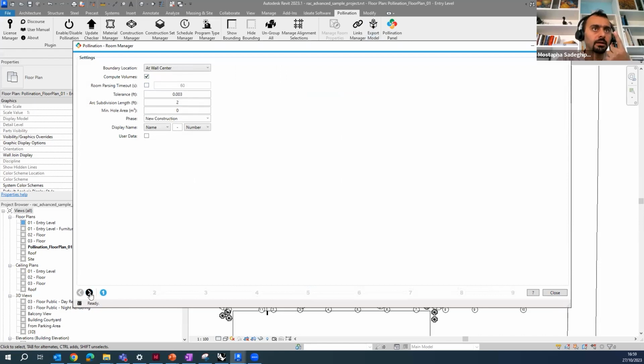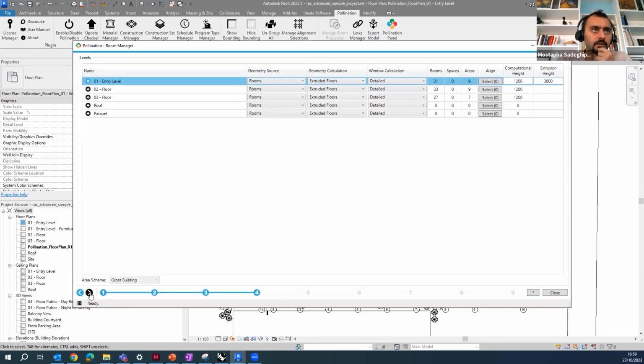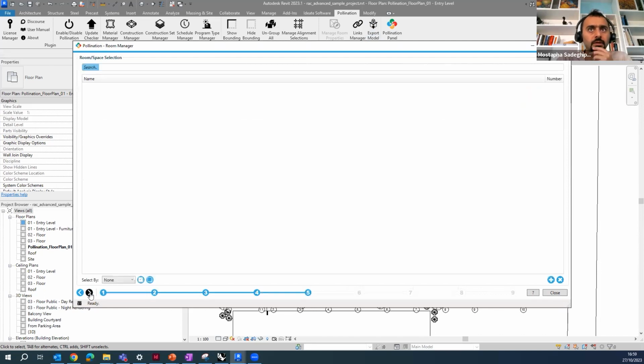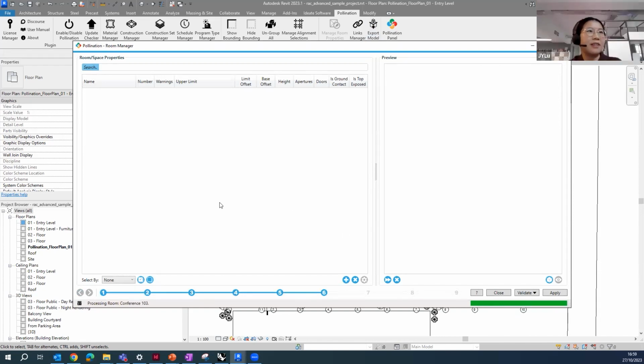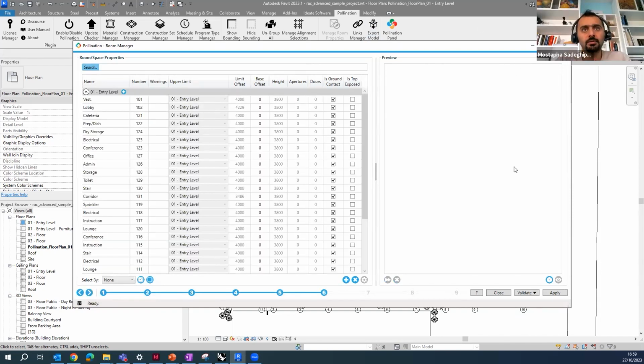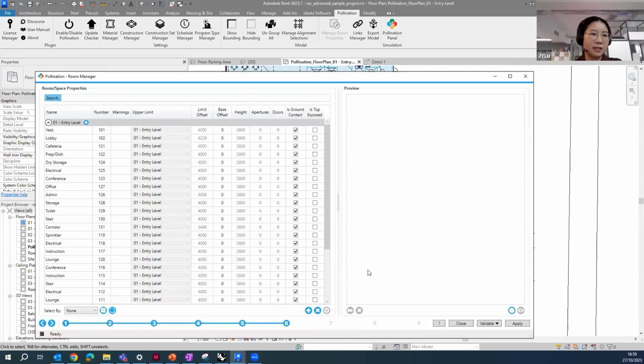There, okay. And then things look good. Go next, next, next. So we see all the rooms. Click next. Click here. Settings. Okay, it's loading. So I think the problem was the volume was not selected, and the other one, you had an active command in Revit that was blocking the progress. No problem. So if you want to stop sharing.